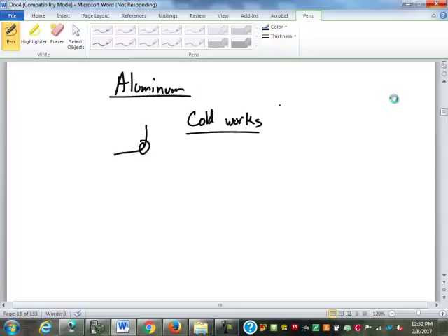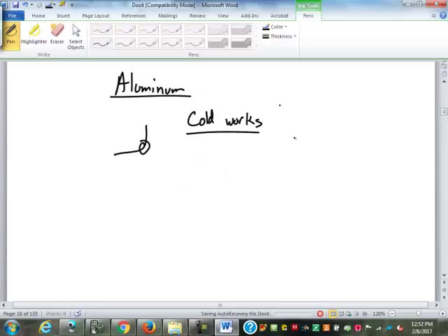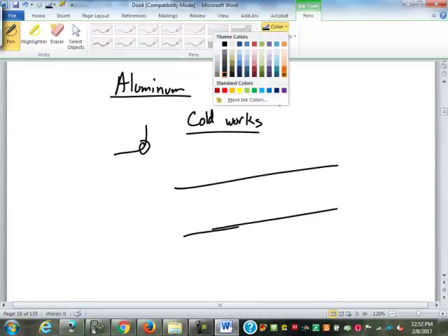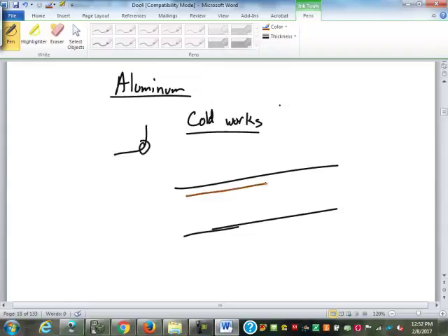Installing aluminum wire, they had to be careful, because if you bend it back and forth too many times, copper wire, you can bend it this way, bend it back, work on it, then finally bend it and shove it in there and attach everything. Well, aluminum, you didn't want to do that. You didn't want to bend it back and forth too many times, because if you did, it would rather quickly, inside your insulated sheath, create microfractures in it.